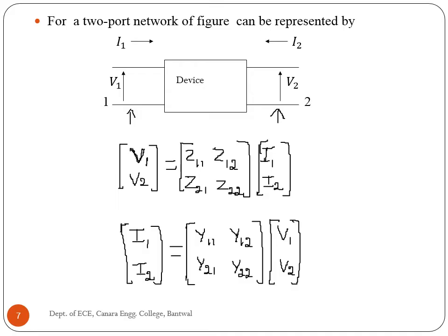For Z parameters, we derive the impedance matrix by selectively stimulating each port with a current source and observing voltage at all ports. Once the impedance matrix is ready, all that has to be done is to multiply it by any new current vector to give us all port voltages.